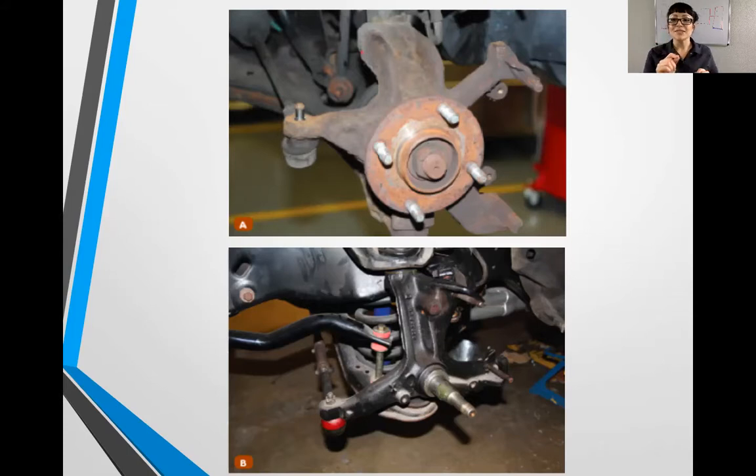So if it uses taper roller wheel bearings, it's going to have a spindle. If it does not, it is going to have no spindle. So these types of hub assemblies have no spindle. This one has a spindle but no hub. So just something to think about when you come across this, and people talk about terminology. A lot of times to lower vehicles, you can buy knuckles where the spindle is located higher or lower to lift or lower the vehicle. You can't do that with these types of hubs, or these types of knuckles. You'd have to lower the vehicle in another way.